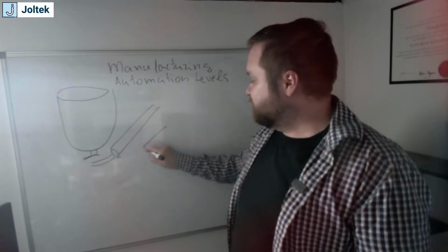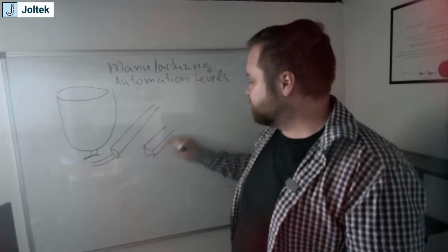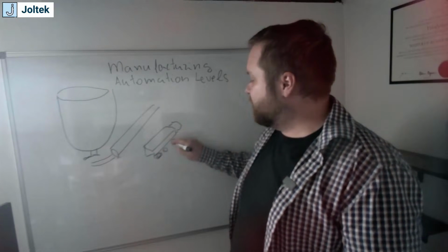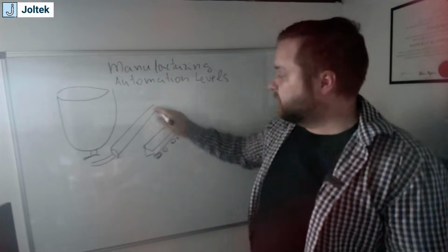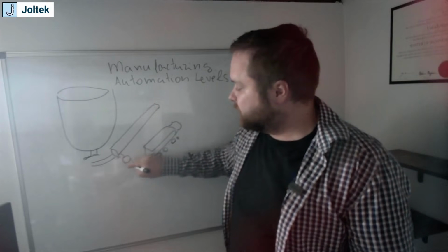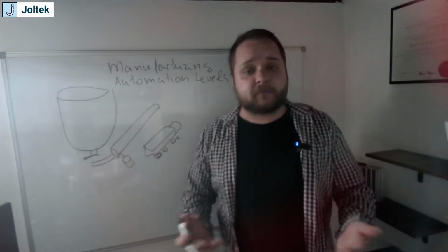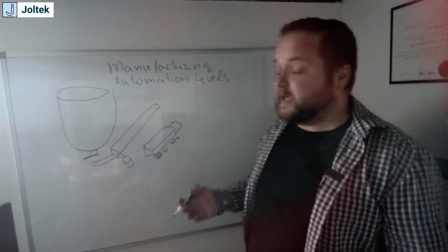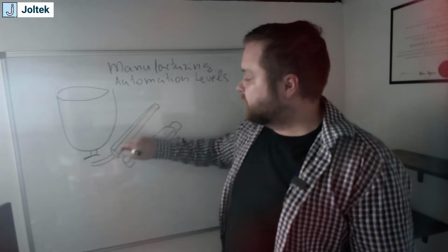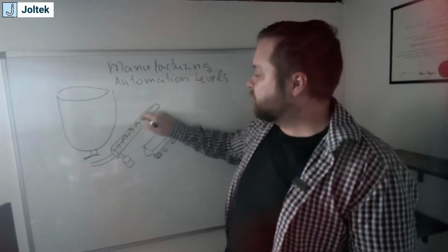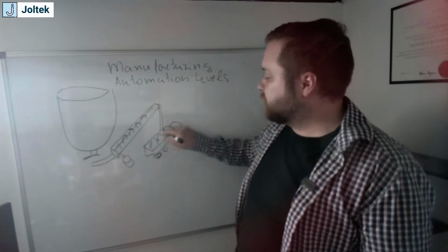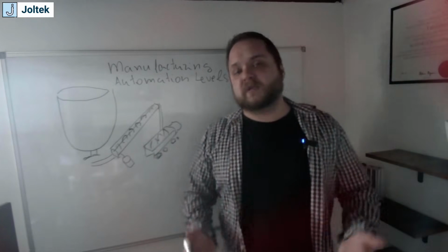And here, once again, I'm going to make this very crude drawing of a truck, right? If you have something as simple as a truck that's going to simply take the grain and then drive off to a different facility, all the automation you truly need is here. For example, you have a motor that's connected either to a VFD, but really just to a few push buttons that allow you to enable either the VFD or the contactor so that this auger can run. And again, this could be a different conveyor. I'm just going to create this very crude drawing where the grain goes into this truck and then the truck can drive off. Do you need a PLC in this case?